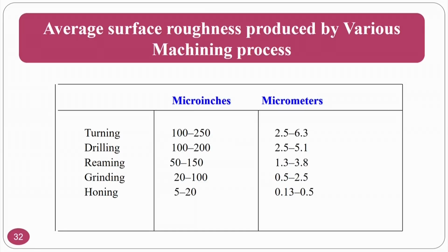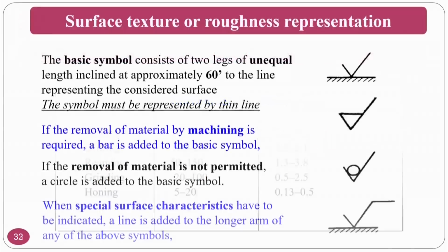Okay. So, normally the surface roughness in a turning operation in micrometers, you can see here. These are the ranges 2 to 2.5, this is the old values, very old, we have taken from the old book. So, these are slightly higher side. However, nowadays with the sophistication of the equipment and all those things, these values can still go down.